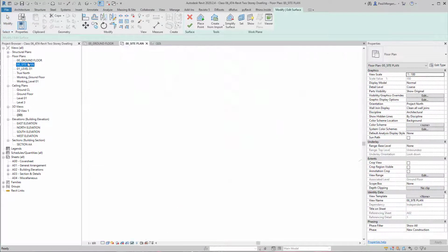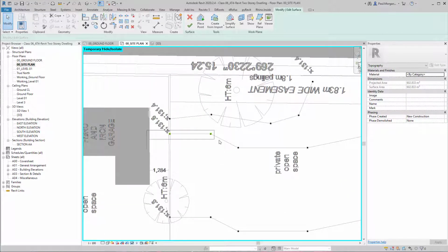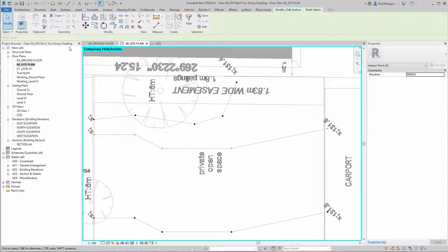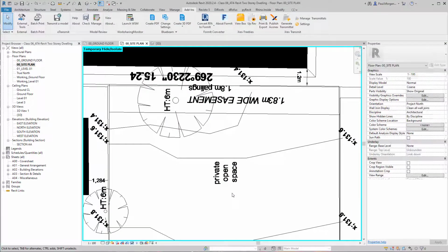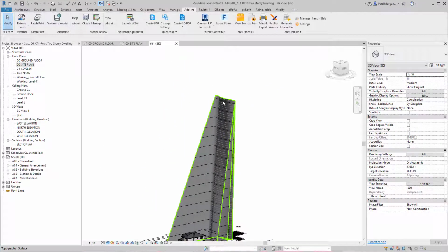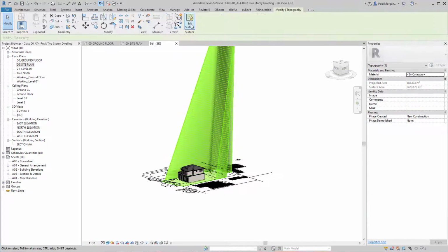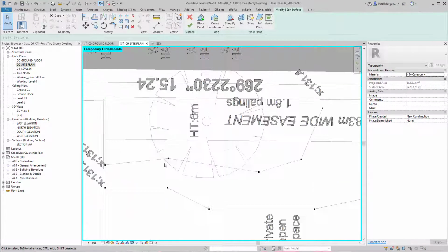So I'm going to go back to the site plan and take these ones here. These are 130.16. So I'll select these points. I can hold down Control to select more. And then up here in the elevation, I just change that to 131,600. Click Enter, and they're now moved. So if I say OK, this is going to look pretty weird. You're going to get something that looks like this, because these points have been moved, but all these are back at the original position. So it's fine, but just notice that that will happen until your points are cleaned up. So I go back to my site plan, and I'll continue on.